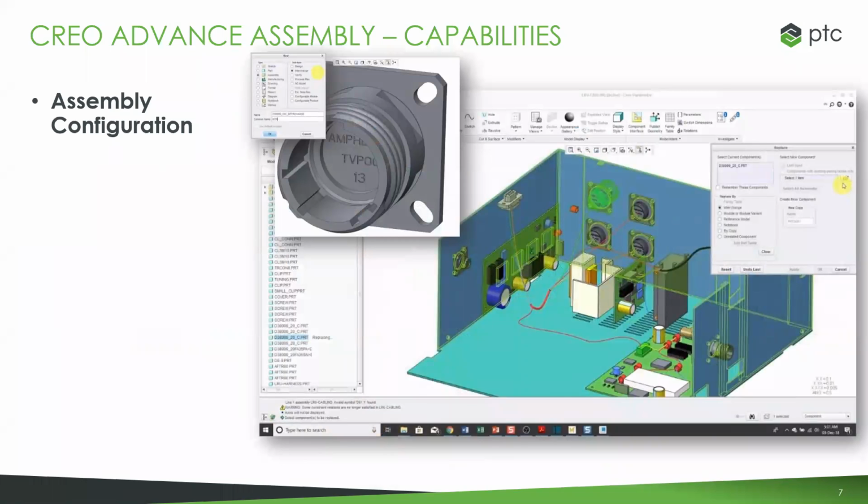We also need to work with assembly configuration. When we're dealing with things like interchange groups, whether it's fasteners, attachments, that are all going in the same way, I shouldn't have to spend time doing each one individually. Assembling each one, aligning each one. This process needs to be faster, needs to be easier. If you have a fitting, make it mount, pick the face it goes on, and select the location. It doesn't need to be complicated.